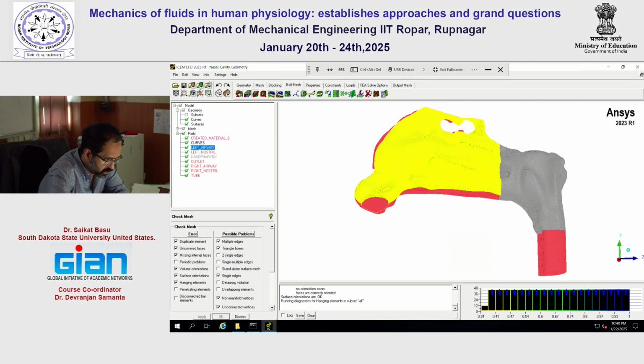Okay, so it's back. It's still going on. So if we have this already tetrahedral mesh, for that we are using the prism layer. Is it possible that it is a well-defined mesh, but it may get unstructured after injecting the prism layer? It can happen. So we will do the mesh quality check even after building the prism mesh as well.